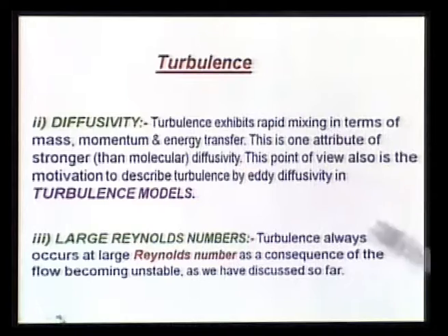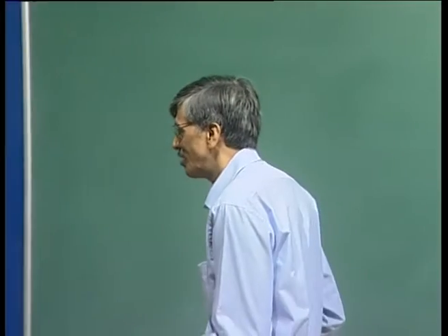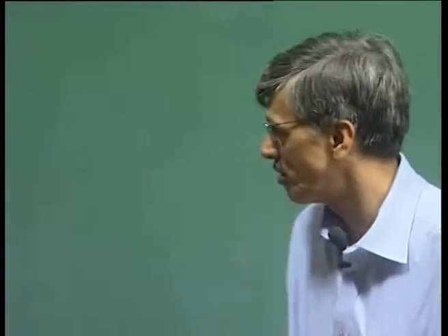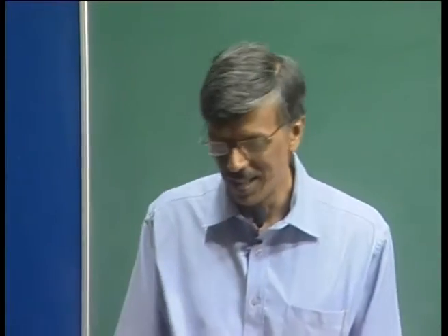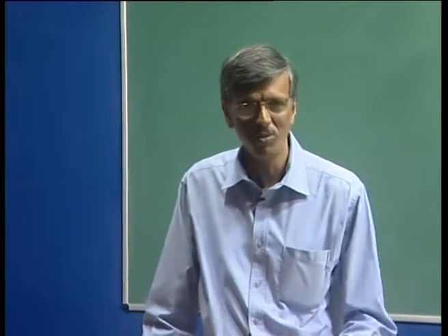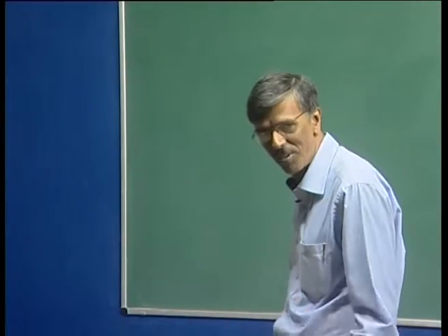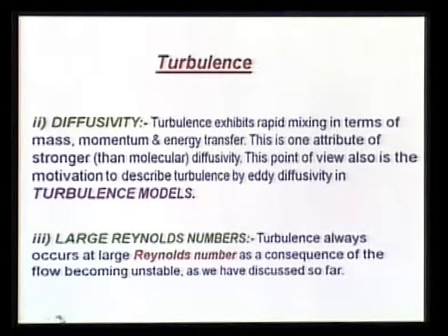And unfortunately, this point of view also is the motivation to describe turbulence in terms of a diffusivity coefficient. That is what goes by the name of eddy diffusivity, which is modeled most of the time in turbulence models. But please do not try to understand, in the name of engineering fluid mechanics, turbulence in terms of the coefficients of turbulence models. That is far from the truth. This is one of the attributes of turbulence, that you do have enhanced diffusivity. That eddy diffusivity is associated with the eddies.